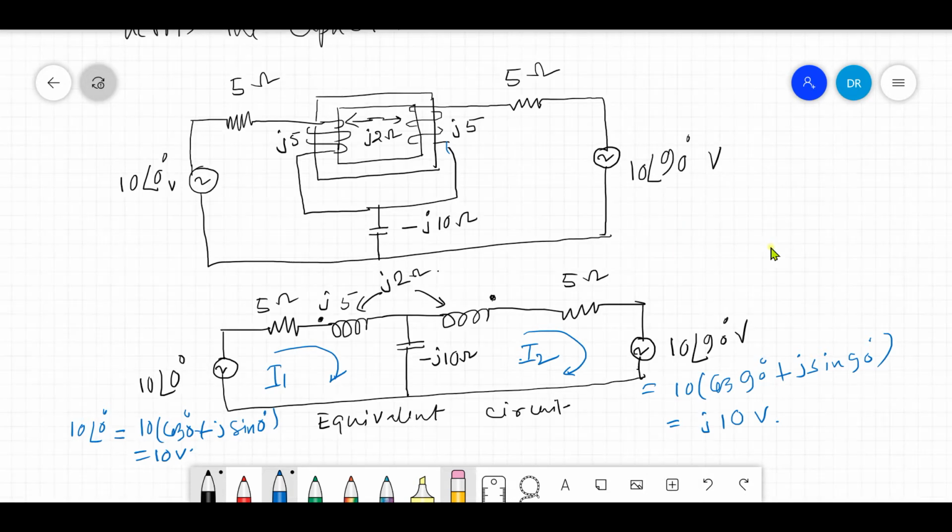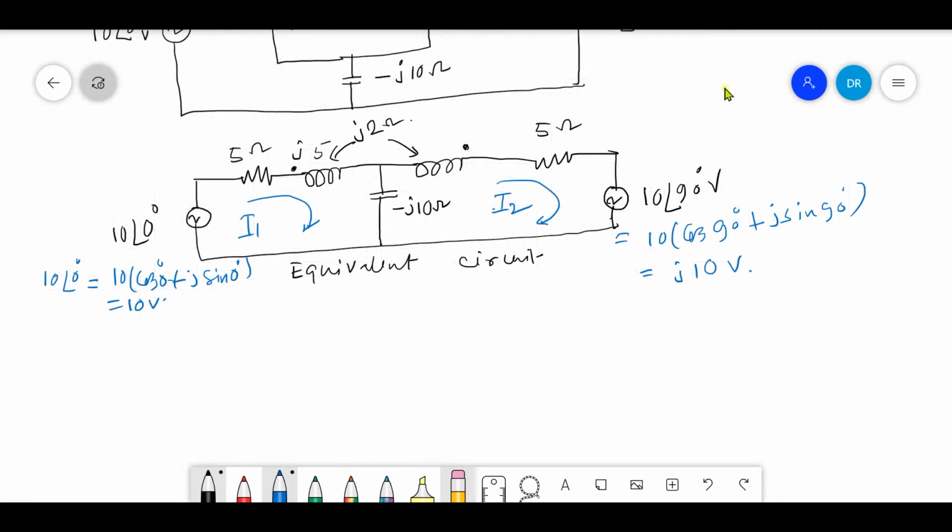In these connections, the two coils are connected in series in such a way that their induced EMF are of opposite polarity. That is, in coil 1, current is entering the dot, and in coil 2, current is leaving the dot. So the mutual inductance between them will be negative.